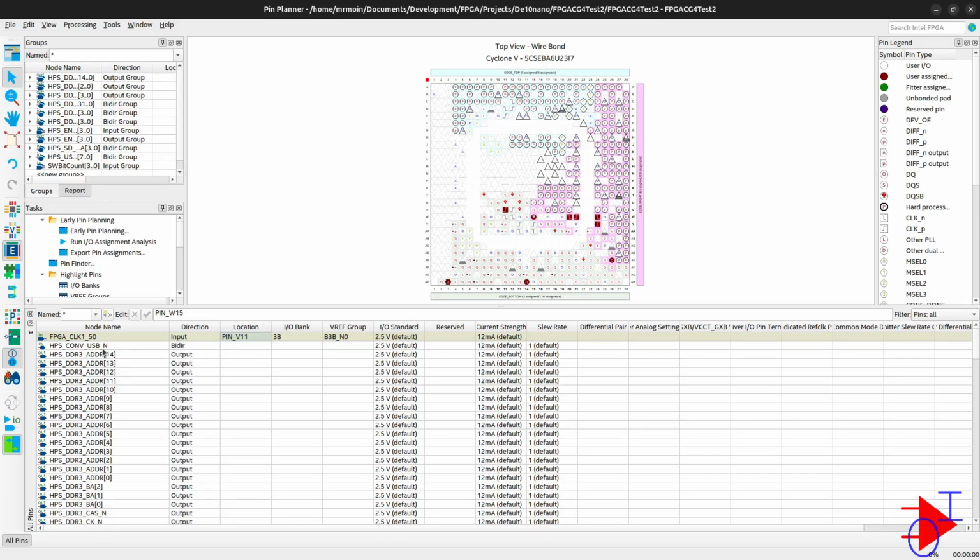So the naming is very important as well. I'm not sure exactly if it has to be exactly the same or not, but I know when you make that component connection, it knows exactly which one of these are supposed to be connected to which pin on the Cyclone 5. So as it executes, the compiler figures out these connections and it automatically assigns.